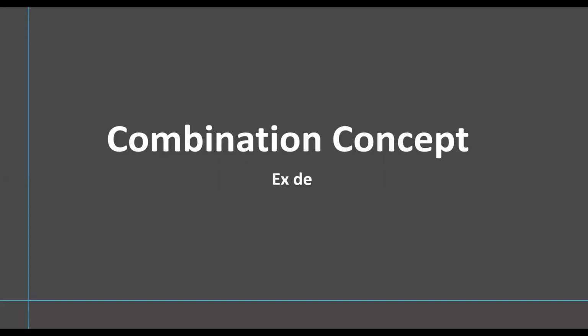With the introduction of EPLs, we have a very nice little string now, and it's called an EXDBEBGB. Quite a mouthful. Basically, don't get too worried about it. It's just an EXDE. It's telling you that the EXD is category 2 equipment for zone 1. It is telling you the E concept is also category 2 equipment for zone 1. And it is telling you that both of those, the whole machine, is for gas and for category 2 zone 1. Again, repeating themselves over and over again. So nobody should come along and say, oh, EXD, I can put that in a dust environment.